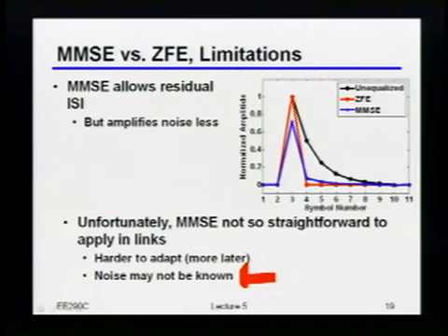If you do indeed estimate the BER, is it equivalent to doing an MMSE or is it not exactly? Well, you could do what's called a minimum BER equalizer, and some people have done some work on that. The biggest issue with most of them is that if you really want to do it the quote-unquote right way and really minimize the BER, it takes a very long time to measure 10 to the minus 15 or 10 to the minus 20 for each and every single point. I'm just asking if you do go down that path, even if it takes long, will that actually be MMSE? Is it exactly the same? No, not exactly. If you actually did something that purely minimized the BER, that would not necessarily be exactly the MMSE solution.